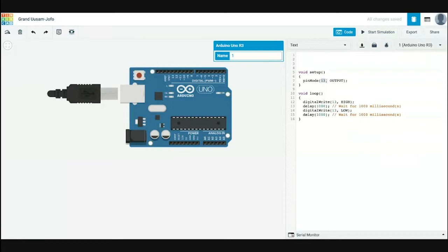This is only really used to test code without having to use an LED for an output, and it only really works to test the 13th pin as an output. Any of those digital pins from 0 to 13 can be inputs and outputs, which means that as an output, it sends electricity, but as an input, it's listening for electricity. Did it receive electricity? If it does, you can use that to make a decision.